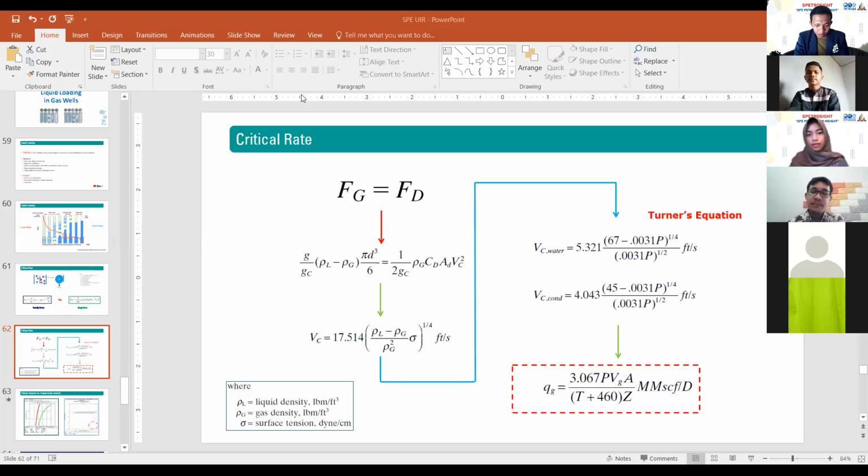Okay, it depends on the case. If your water coning is very severe, the water production is too high, maybe your gas well will be loaded up. Okay, it will die. But if you have suffered from water coning, but your gas flow rate is still high, let's say you have reservoir pressure that is still high, then you can still produce. You can produce the gas and the water simultaneously, but it depends on your reservoir pressure, wellhead pressure, the tubing, a lot of factors.